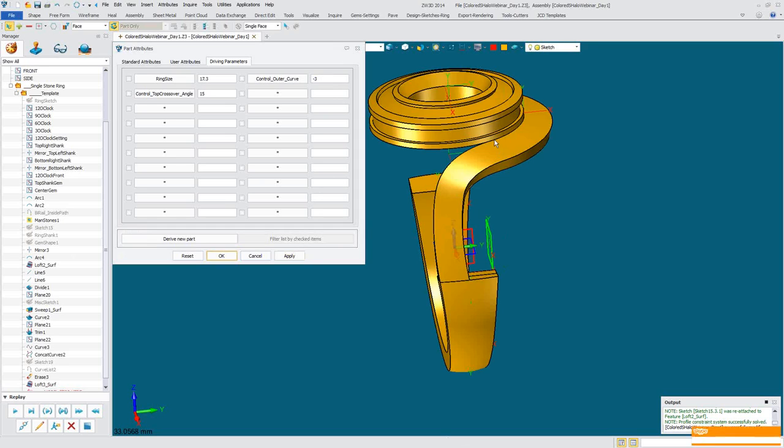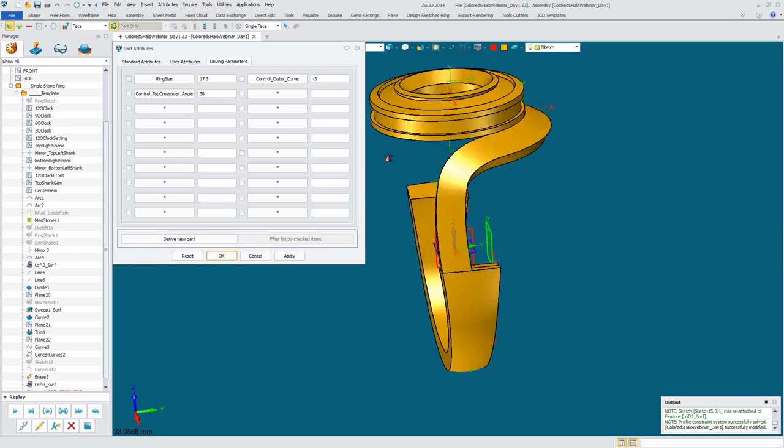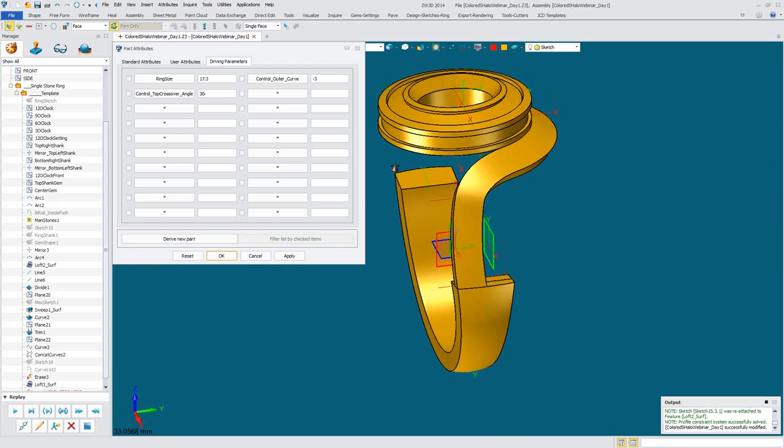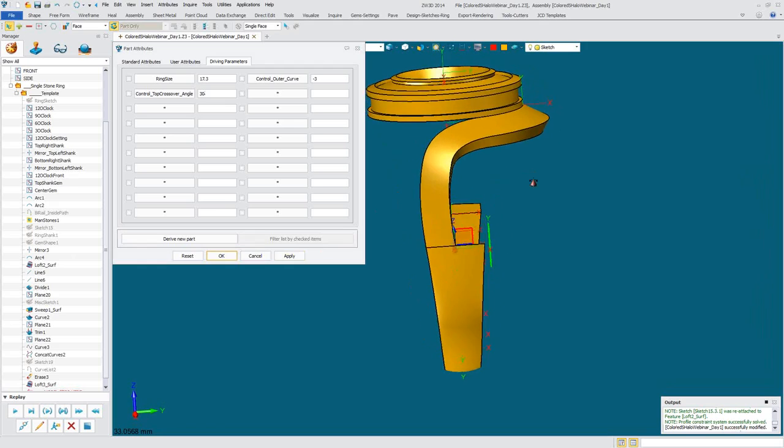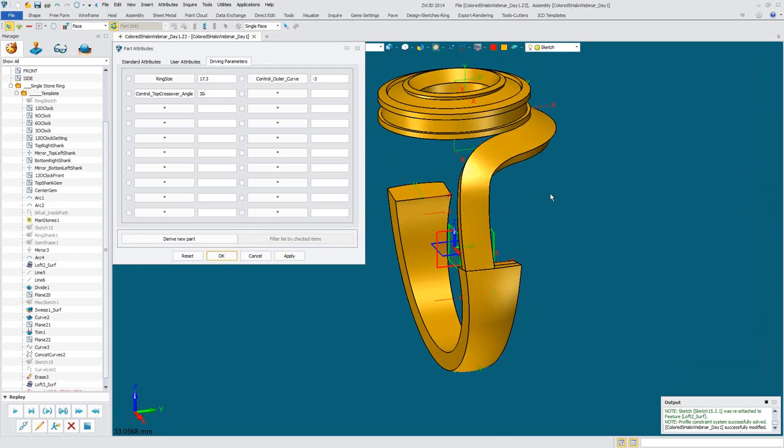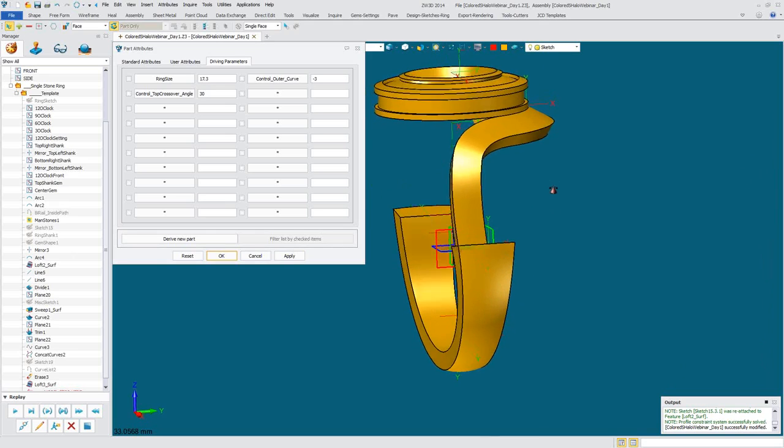It's tighter yet, you see? Okay? So as we're moving the datum in, you got control with how far this is wrapping over. Right? So you got controls. And again, you can put as many as you like in here or as little. Okay? You can work without the controls. You just click and drag. Go in the sketch and just move it yourself.